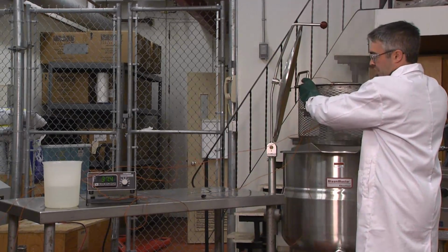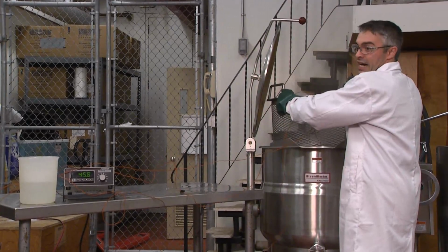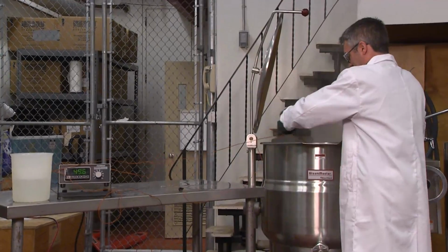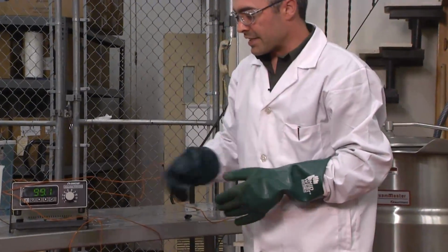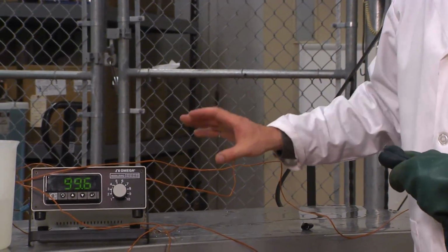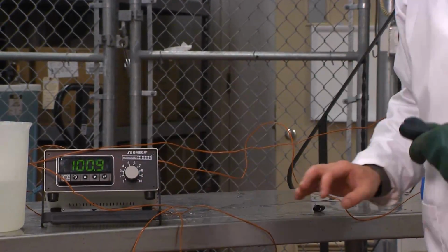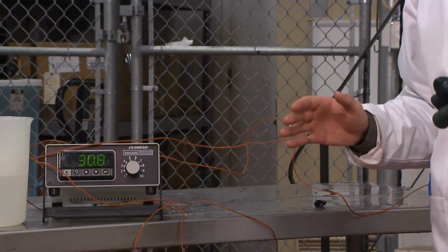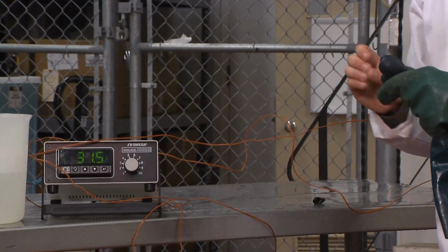At this point, make sure that you have someone starting the timer so you know exactly at what time you begin and at what time you end. We can see that almost immediately the temperature reading for the thermocouple, which has no thermal resistance or very little thermal resistance, immediately shoots up to the water temperature, whereas the temperature of the first object, while slowly increasing with the highest delta T, will slow down the temperature gain as the delta T diminishes.